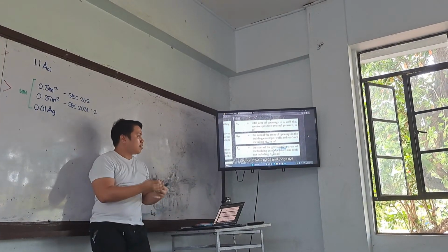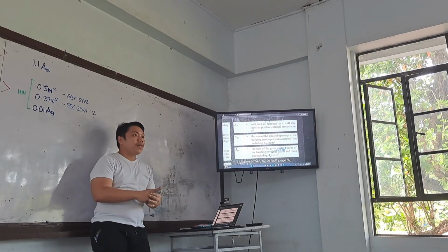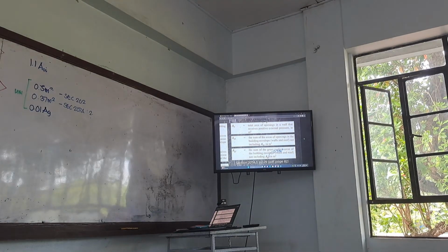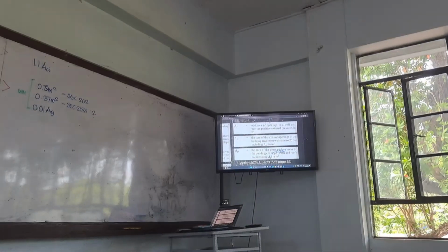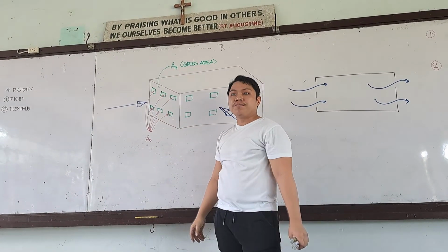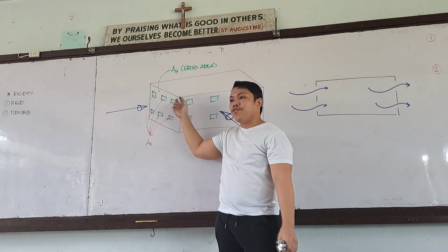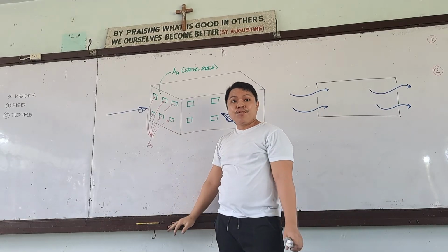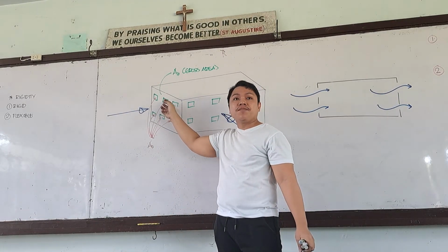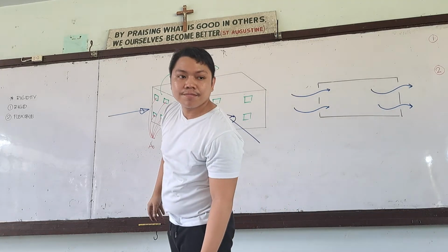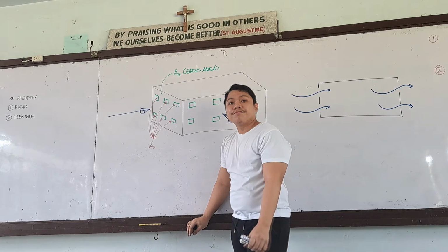Recap that. What about an open building? If our AO, the opening in the windward wall, is 80% of the gross area of our wall, we can consider that as open. For all walls, if it does not receive positive external pressure, each wall is at least 80% open.